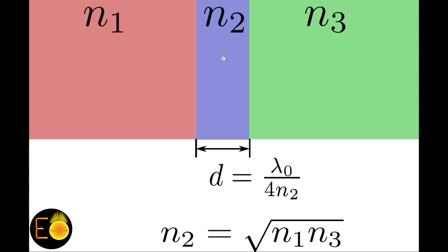Such an anti-reflection coating can be used where you need to absorb most of the optical energy, for example a solar cell. But one of the main disadvantages is that the absorption takes place only at normal incidence. This is very disadvantageous for a fixed mounted solar panel, because the light from the sun will be incident perpendicularly for only a very limited period of time on the solar panels. Therefore you may not get full absorption for most of the daytime. Our purpose is not to improve the efficiency of this particular structure.